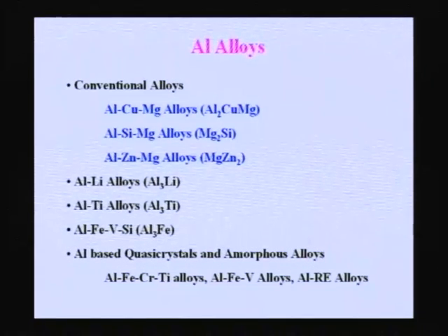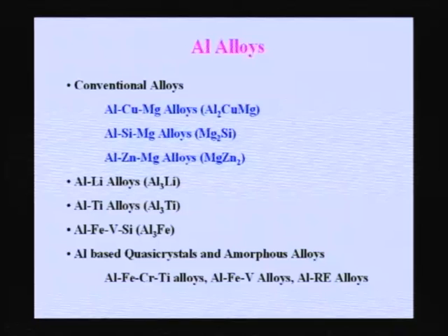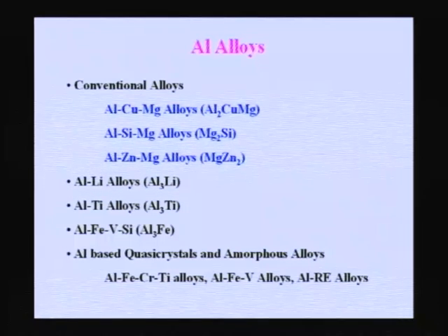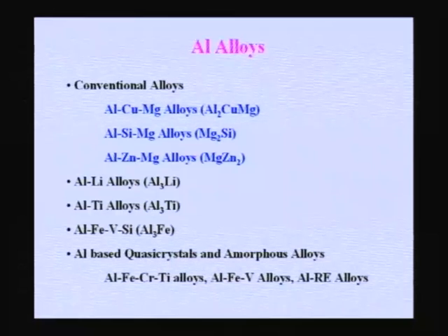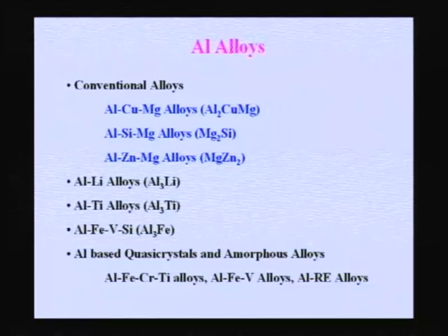I think most of you know it. What is that? It is the lightest metal, not very light, it is the lightest metal. What is the density? Anybody remembers? It is 0.53, the density of lithium. So if you add lithium to aluminum, obviously you are decreasing the density.